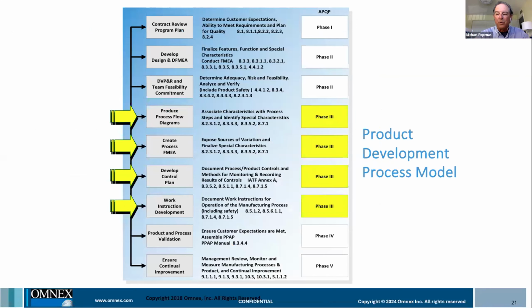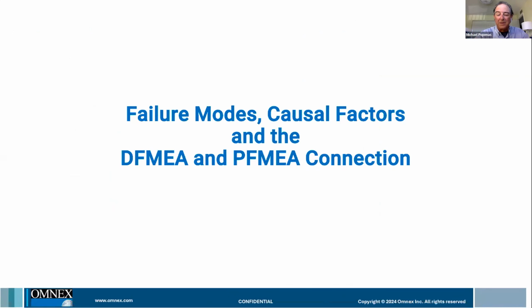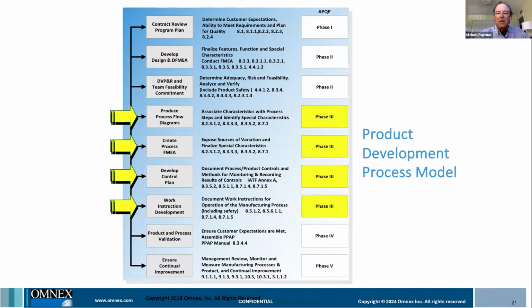And the drivers for those that we're talking about next here are design FMEAs and process FMEAs. There certainly is a connection. Design FMEA is when the engineering team, the product development team, is looking at the failure modes to either design in controls in their products to address those failure modes or eliminate them. Now, the RPNs or AP values that come out of that exercise, that is an engineering exercise. And that is where we find the opportunity to really apply design for manufacturing and assembly rules to specific designs, specific failure modes.